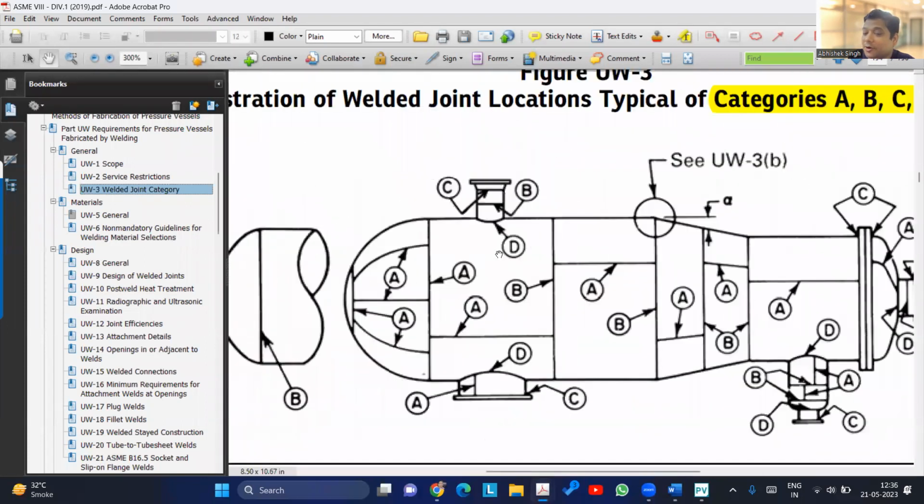Okay. Now just talk about C. Which type of stresses will be governing in C? Longitudinal. So it becomes similar to B. See, actually, if I extend the lip and make a butt weld, it is as good as B, right? It's very difficult to differentiate B and C. It's very similar to B, isn't it? Yes.